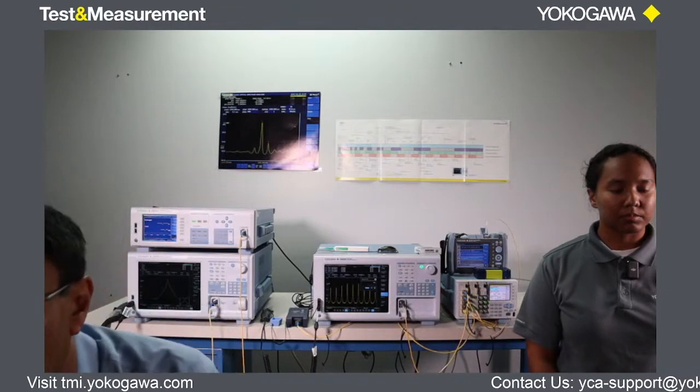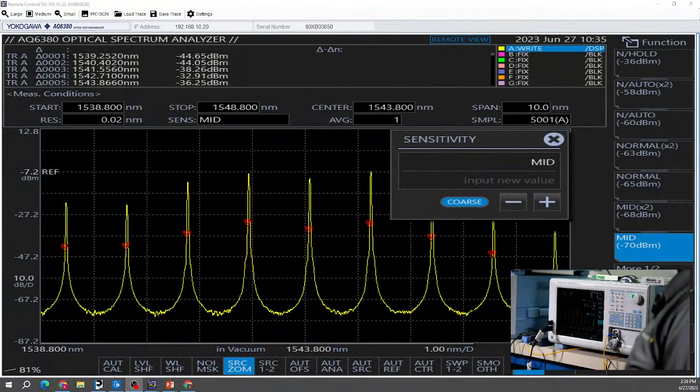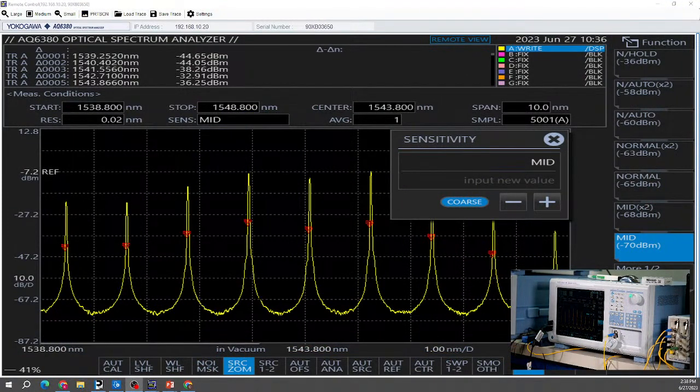Question is, what are you connecting the instrument to software? Is it USB? Actually, we're using the LAN port. The LAN port is much faster, and of course we had GPIB in the beginning, but when we came up with this viewer software to be able to connect it remotely, we found the LAN port was the fastest way to do it. The USB is there mostly for, as Danielle mentioned, the mouse, the probe, the keyboard, but for remote command it is mostly the GPIB and the LAN port for highest speed, of course, and probably most cost effective.